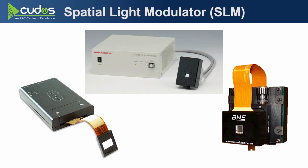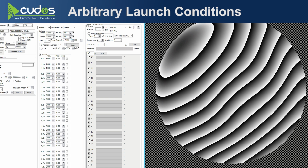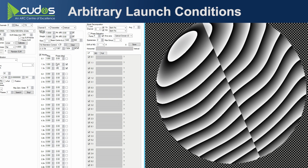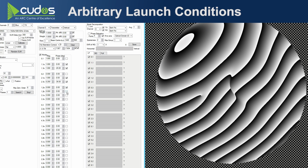When you build an SLM mode mux, you're not bound to any particular fiber type, number of modes, or particular mode basis. Those are all just software changes that you can make at any time. So for instance, here's my interface in the lab. You can just dial up whatever mode superposition you want, assign it to whatever fiber you like, adjust the attenuation of the modes, all software.